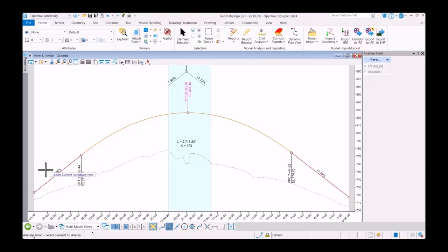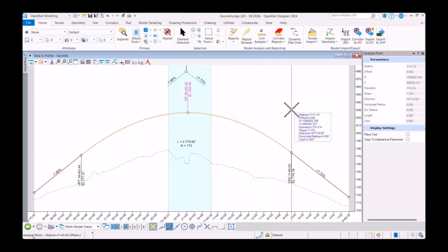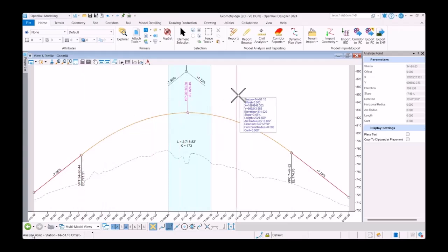And you can also see the chainage or stationing across the bottom, moving from 0 on the right to higher chainage on the left. And any tools that you use would follow that as well. Now, this is not stored with the profile. You can toggle it back and forth anytime you want. So if it's convenient for you right now to work right to left, and then you want to work left to right, just swap them back and forth as you need.